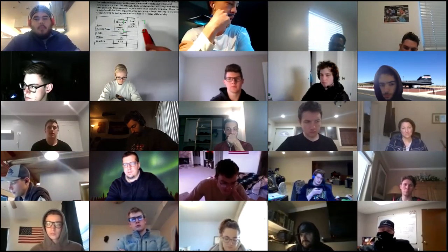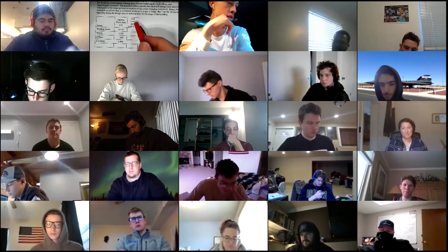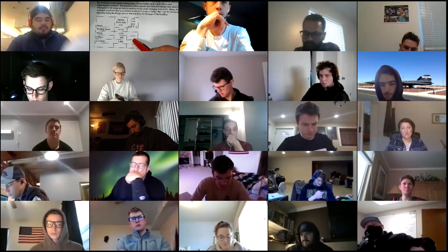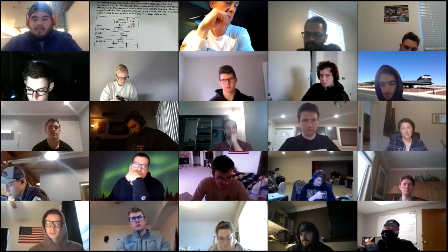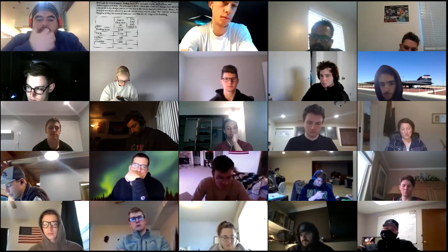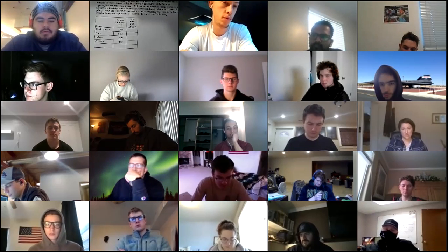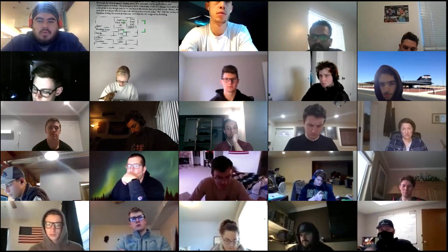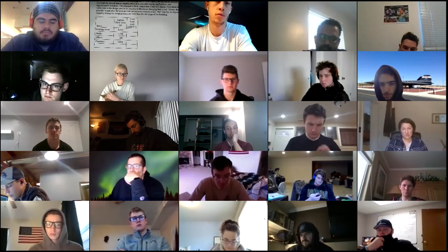And so what we're going to do is go and figure out what live load values there are here. And then we're going to try to figure out how we might work with that to come up with maybe a unified value across the entire floor space. Because one of the things that's going to happen is during the design, people are going to change their mind about what they want to have happen.